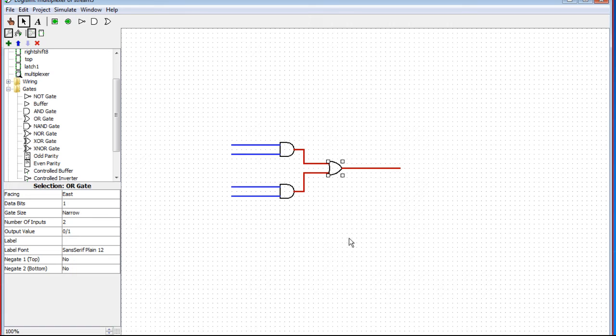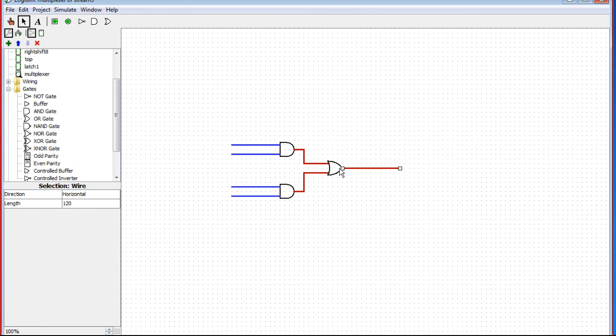But from a pure designing actual silicon standpoint, I'm not sure why you would ever use a multiplexer instead of a tri-state buffer. I mean, the only reason I can think of is the multiplexer is always going to be driving the bus with a logical value, whereas with tri-state buffers, you can have situations where two buffers are driving at the same time, and in that case you get a short circuit, or you can have situations where no buffers are driving, and then you have a floating input. So you can have bad states on your bus with tri-state buffers. With a multiplexer, you've always got logic 1 or 0 coming out of there.